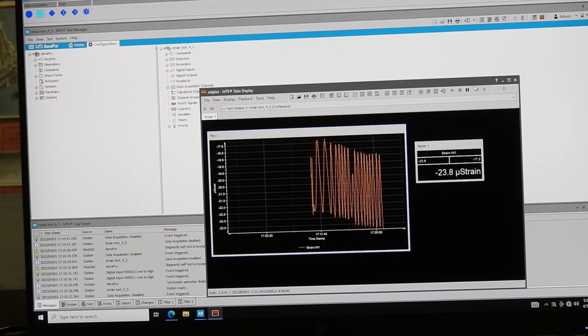We'd have to look at your pin-out for the accelerometers and see how that matches up on this side. The extensometers are a full bridge connection. They have plus minus and then plus minus sensor input. I would hope this would be pinned out the same way, but we don't have any cables, or cut off any ends.